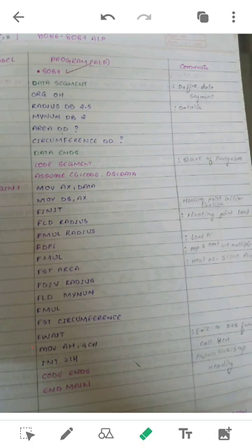Okay, this completes the 8087 architecture: the control word, status word, how the 80-bit stack operates, the data types supported and the range of the different data types, and the instructions you have seen here, and finally you have seen an example of the use of the instructions of the 8087.